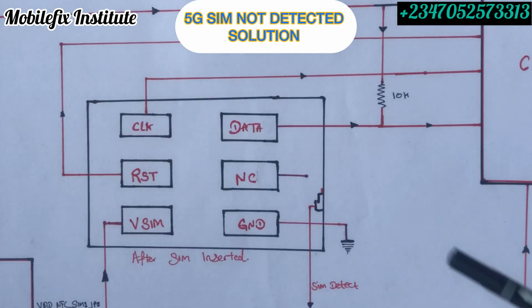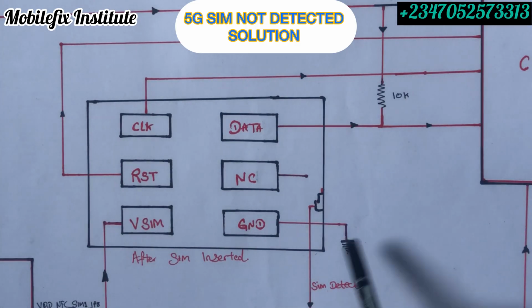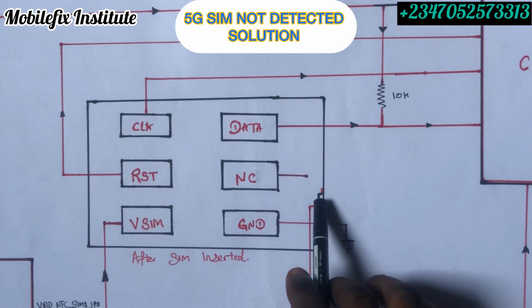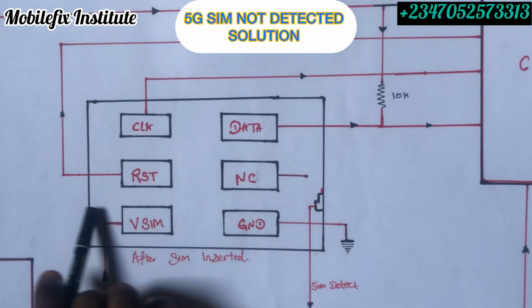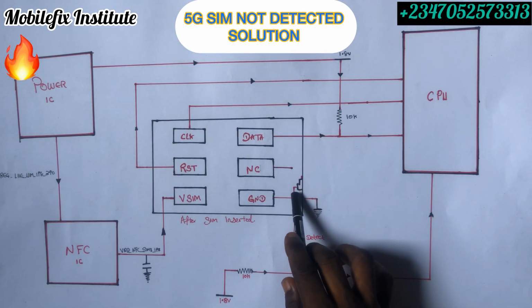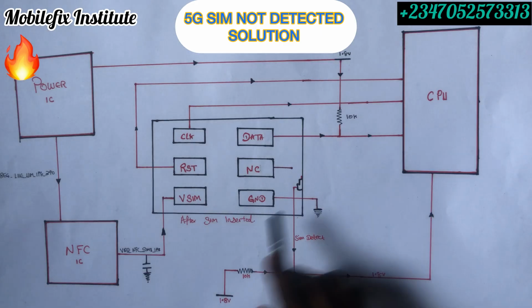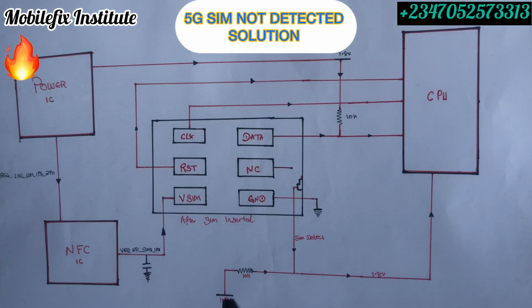Let me explain how it works. This line is always connected, having a logic low. It's always connected to ground, because this pin is linked with ground. You can only disconnect this pin from ground when you insert your SIM card tray. Now, since it is connected to ground, the voltage will not be able to pass, because this resistor is not a fuse. You cannot jumper it. It won't allow the positive voltage to enter the ground, so the voltage will only stop at this other side.